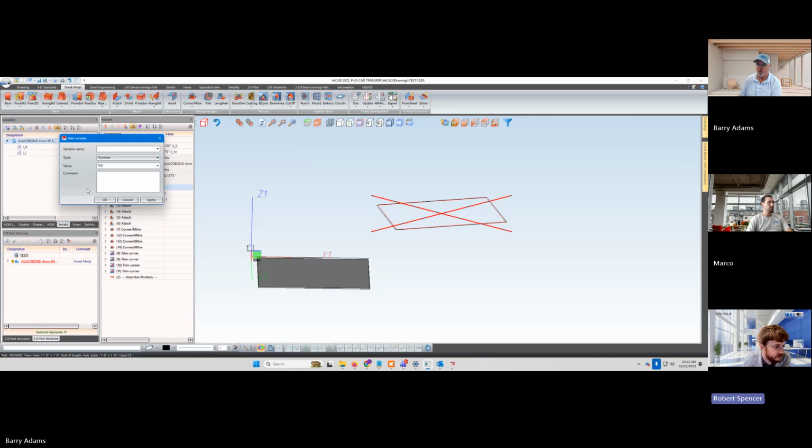So we're going to focus right now on numbers, but at a later date, we can also use edges and surfaces and parts to do more complex parametrics. At the very bottom, a list variable, basically that should say a catalog variable. I don't know why they went with list. It's catalog.